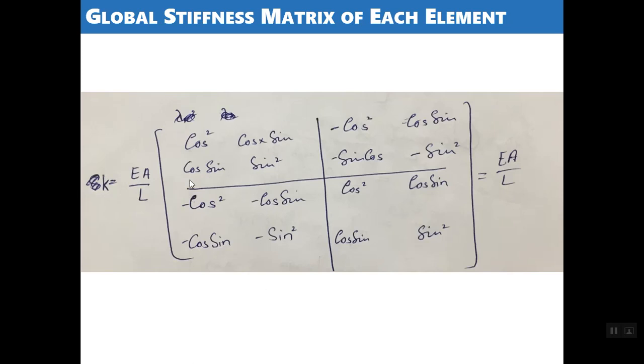That creates one portion of the stiffness matrix corresponding to each element. It is replicated here in the fourth quadrant, and its negative is considered in the second and third quadrant of the matrix. So this is what we have to code now, and we are going to consider this as maybe the last portion. E over L is to be multiplied with the whole matrix.